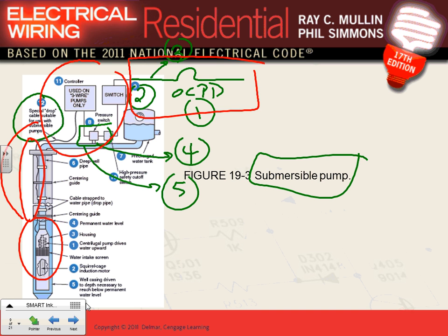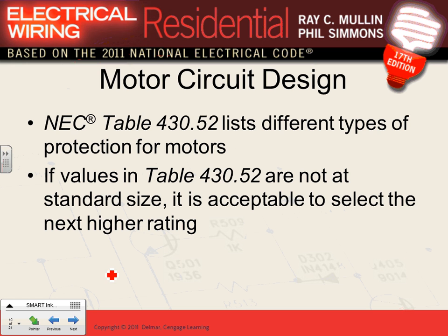We provide an overcurrent protection device, a feeder, and a disconnect right next to it if the manufacturers don't provide that disconnect. Cool? Any questions, guys, about these? Can I have a thumbs up, Chad? We know how it works, and we know what we need. Later on, I'm going to do some calculations about the electrical requirements for this pump. I'm going to come back to these, guys.